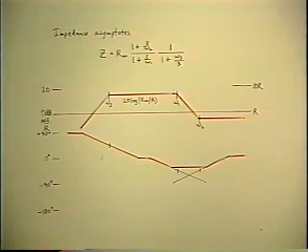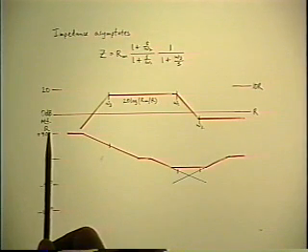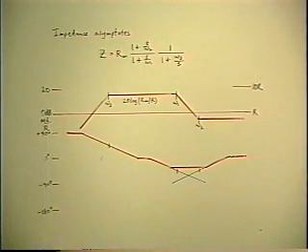Unfortunately, a lot of people don't bother doing that. They just write a 0 dB scale for impedance. And if you don't say what it is, the implication is the reference resistance is 1 ohm. Maybe. Maybe it's 1K. But you don't know unless whoever drew it specifies what units you're using. So to be strict about it, you should always use or specify what the reference value of resistance actually is.